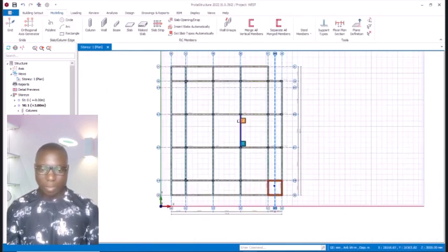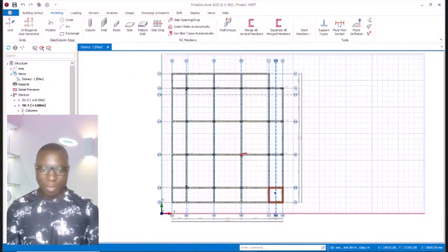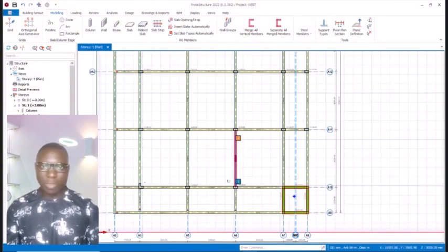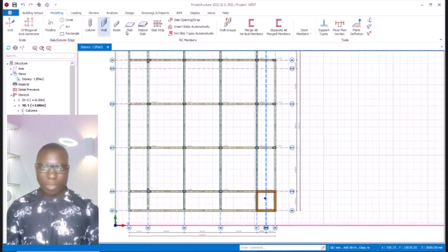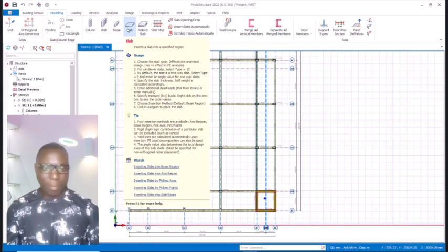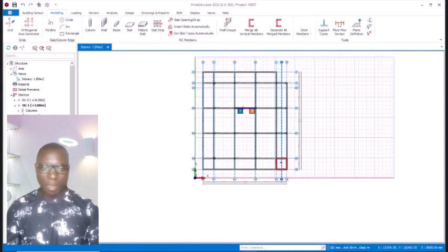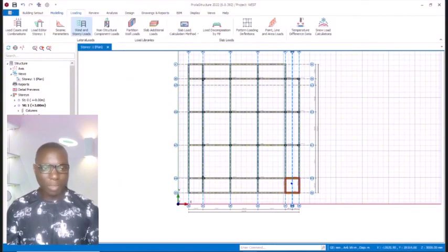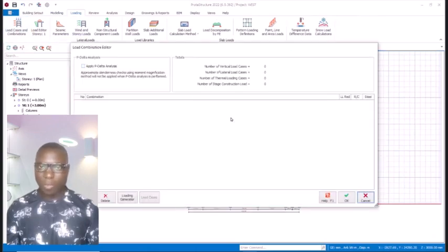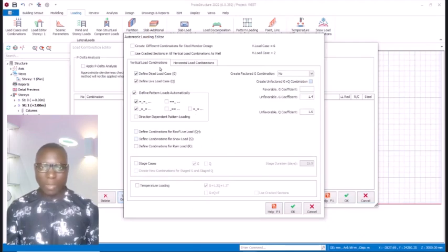Okay, so having done with this, at this first floor we are going to be having a solid slab at this first floor. Right, solid slab. So we'll proceed to generate the slab system. Okay, so I'll go to the slab tab right there, but by then I will have to enable my loading combinations successfully. So for me to do that, come over to where I have loading options. In that loading options, see load cases and combination. I click in the provisions. In this dialog, I go to loading generator, and then I'll quickly activate the vertical load combinations.